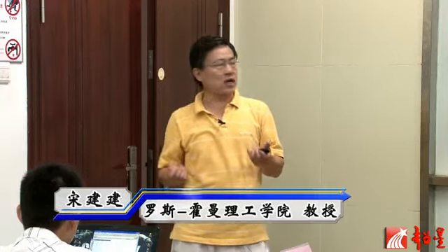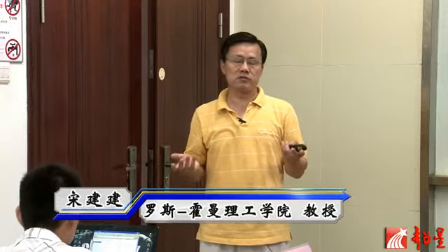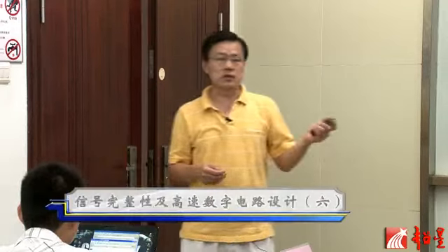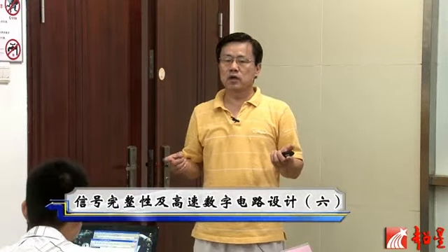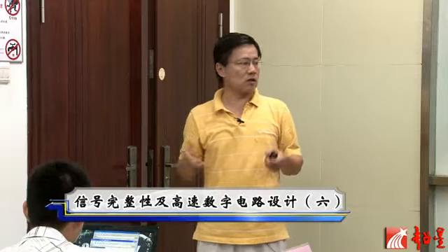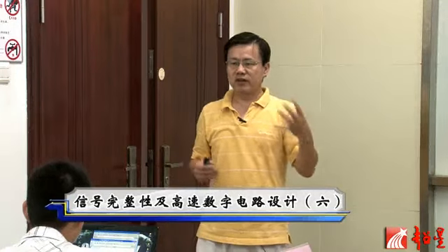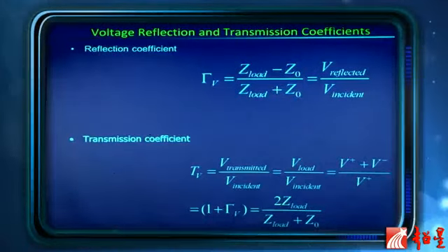From a digital design point of view, we're interested in square waves. This afternoon, I'm going to introduce square waves to you, which is why the examples I'm using all use a step function. Transmission line theory was developed for microwave applications where sinusoidal waveforms are more important than square waves, but from a digital point of view it's actually much simpler, because we just have square waves.